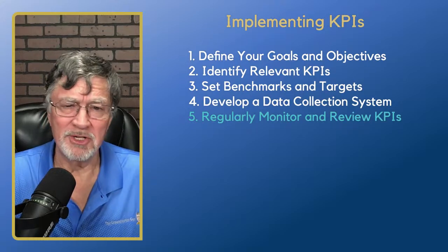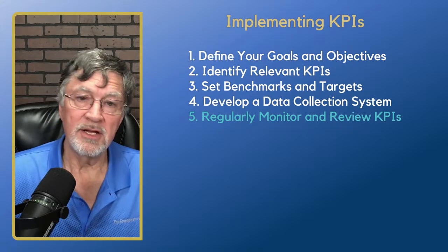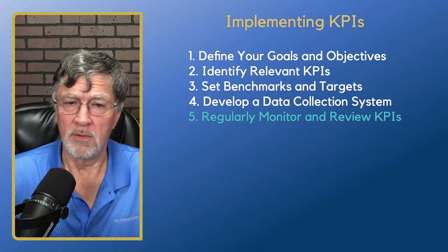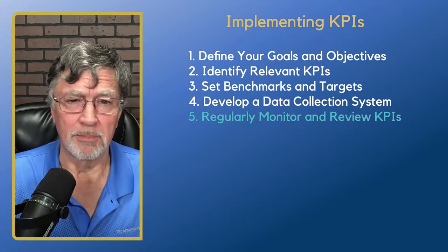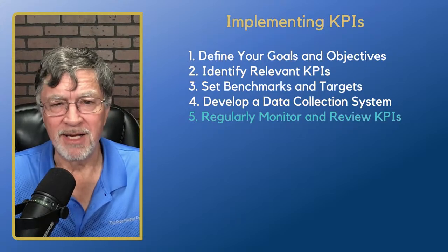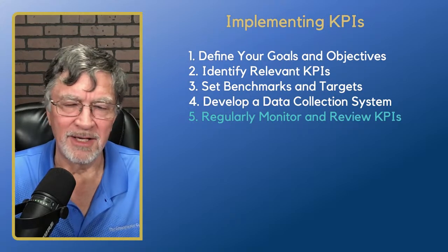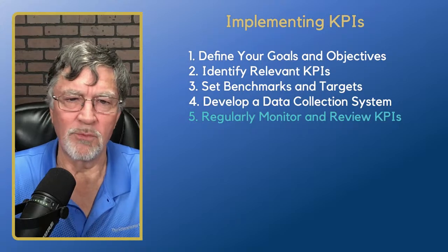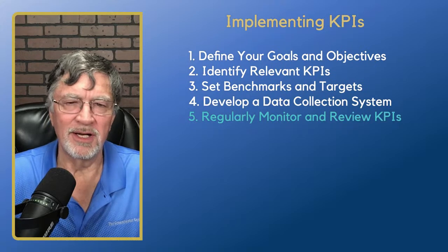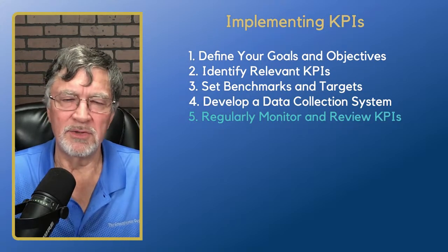But unless you put it on a chart and actually track it, the trends become a little clearer, and then you can start to dial in on what a potential solution is, or even more basic, identifying what the problem is, and then developing a solution around that problem. But you may never see it. Even though we're looking at our coliform data and checking to see if we're in compliance, somebody remembers, well, we had a hit last year and then it went away, but I don't remember exactly when that was.